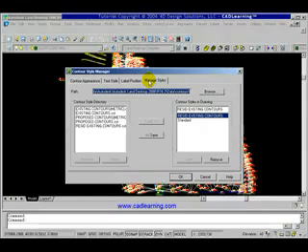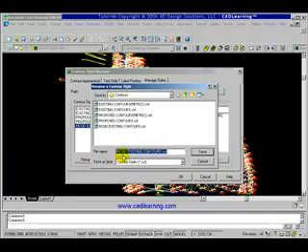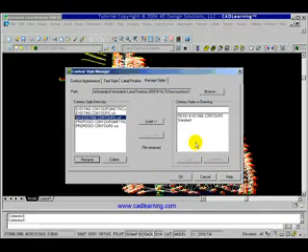We'll go to the Manage Styles tab, and we can save our settings. We have several settings available, and we have a couple of settings in the drawing right now. We have one called Residential Existing Contours. We'll save that, overwrite with changes. Then we're going to rename it so that we can recognize it for our Glen Hills project. We'll rename it Glen Hills, or GH Existing Contours.